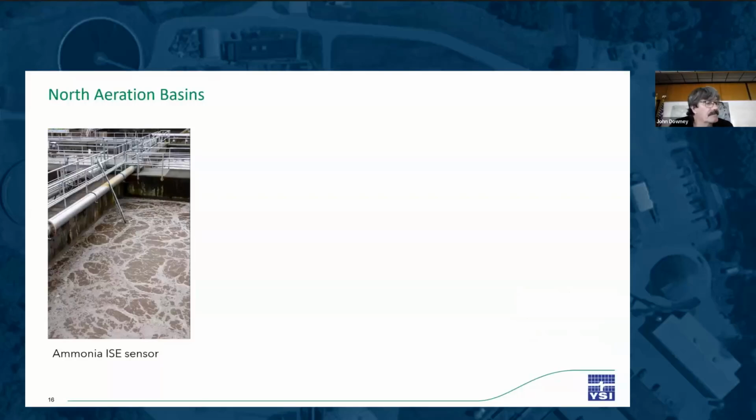These are some good shots of our sensor placements, and these are all in Basin 4. On the left, you see an ammonium sensor, and it's located at the spot where currently we are seeing less than 1 to over 4 parts per million in a single day. And that's been fairly consistent. I'd say just in the past 5 days, that high end is rising to over 5.